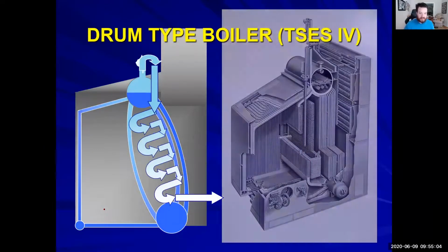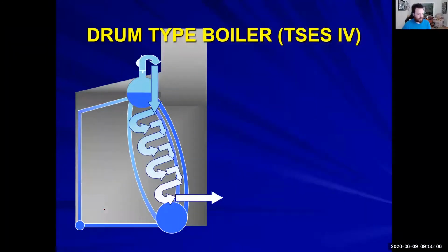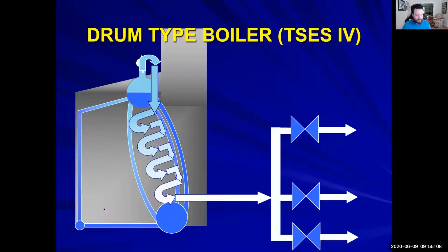So from the superheater and out of the boiler. Now, the big thing I want to talk about, we'll only talk about one boiler right here. This is the one instance on a ship where we don't have a backup. We can steam with one boiler, but we're always going to use both boilers at full capability the entire time.